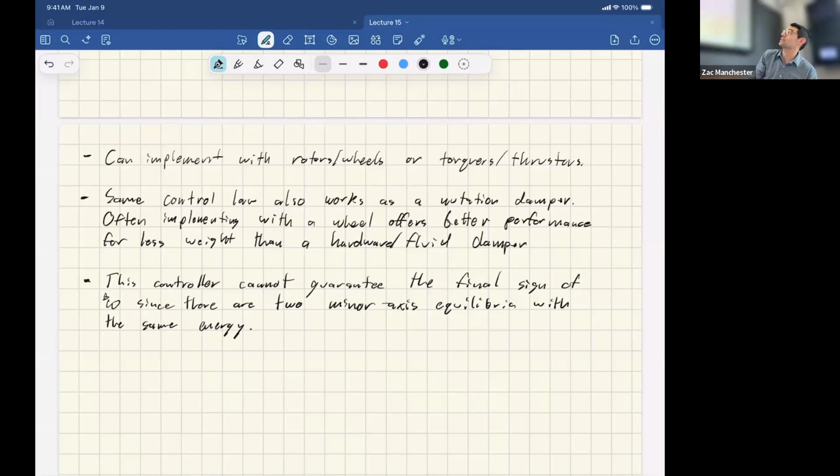So then what I do is just add those together. I take that weirdo averaged linear thing and add it to the quadratic thing that I had before. And now what that gets me is the best of both. The quadratic thing pushes me out of the major axis spins, and the linear term makes sure I head towards the North Pole and not the South Pole. And then there's a whole bunch of math details about how to actually calculate the controller, which are irrelevant here. This is all how to do that periodic averaging trick.